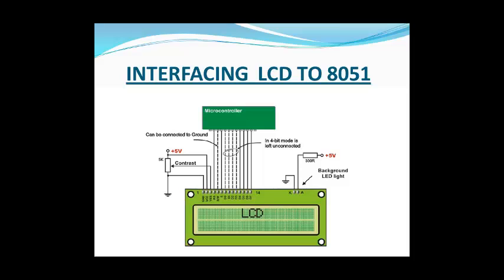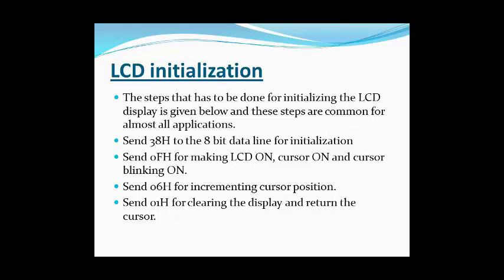We can see that pin 1 is connected to the ground, pin 2 is connected to the VCC, and pin 3, VE, is used to control the contrast. Pins D0 to D3 are left unconnected in 4-bit mode, and the read-write pin is connected to the ground during the write operation. Now we'll have a look at how to initialize the LCD.